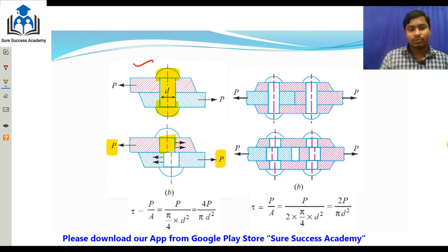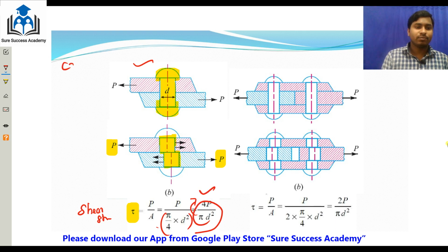The stress due to this is called shear stress. Shear stress τ is equal to P by A, which is P by π/4 d², that is 4P by π d². So this is case 1.